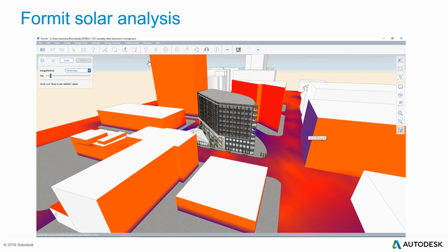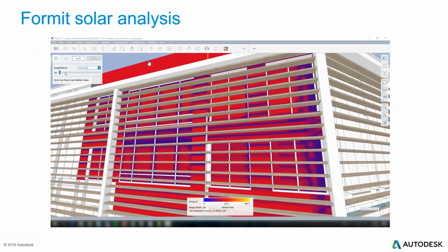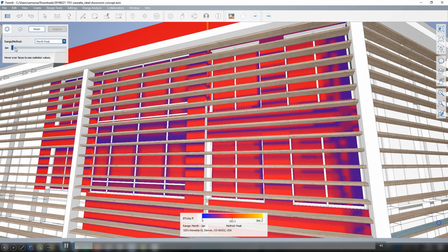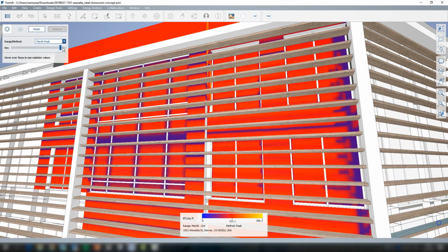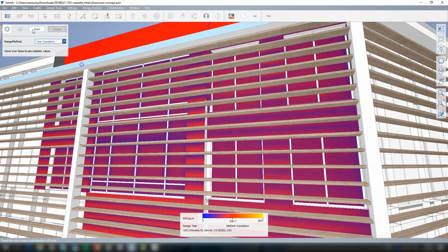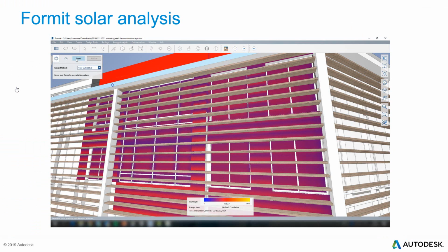which very quickly tells you what effect your conceptual design, your conceptual model, has on the surroundings. So you can see this colorful map very quickly. It also can be used. So the solar analysis can also be used for different scales, much smaller scale, when you can, for example, see what effect this kind of shading, solar shade, will have on your facade, right?